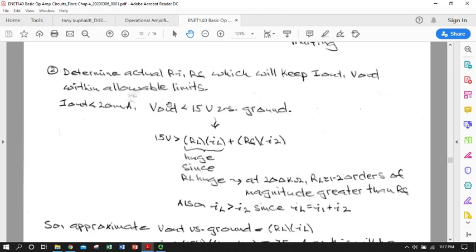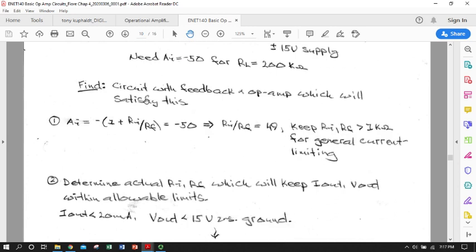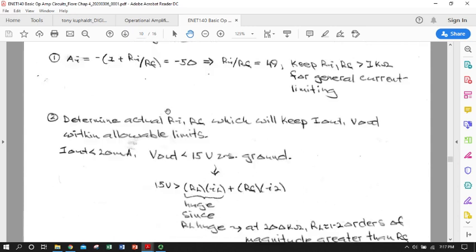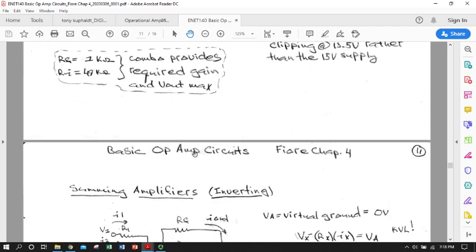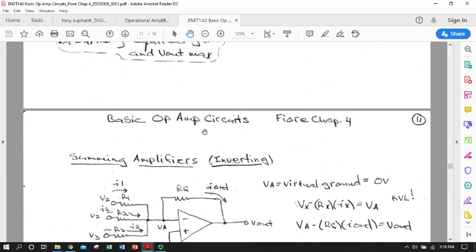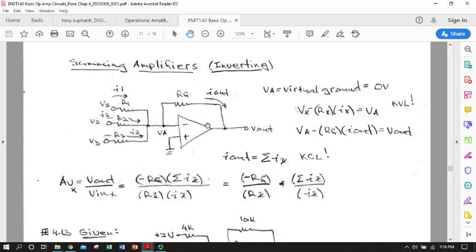Going through the exercise of an allowable voltage drop versus ground for V out and confirmation with I out max really had a lot to do with using our current gain and then saying, for this gain, what kind of input signal would we allow such that our output signal stayed below our rail voltage clipping limit. So a little bit of a real op-amp characteristic consideration there.